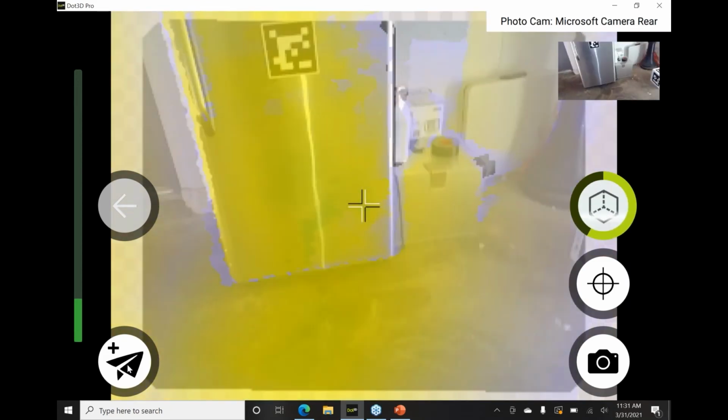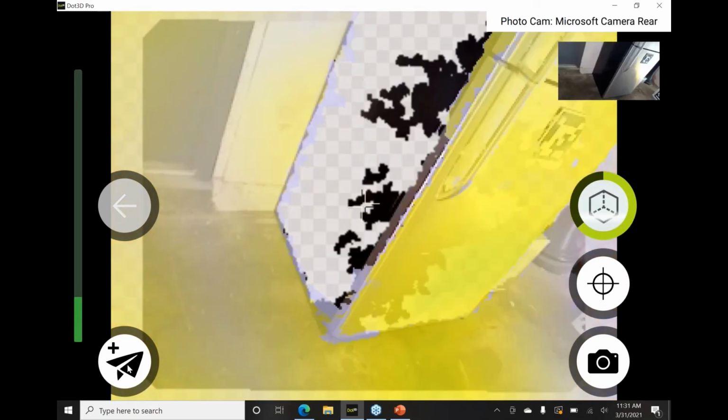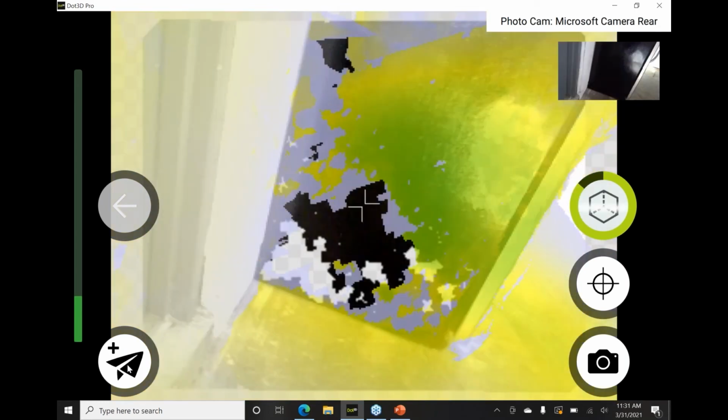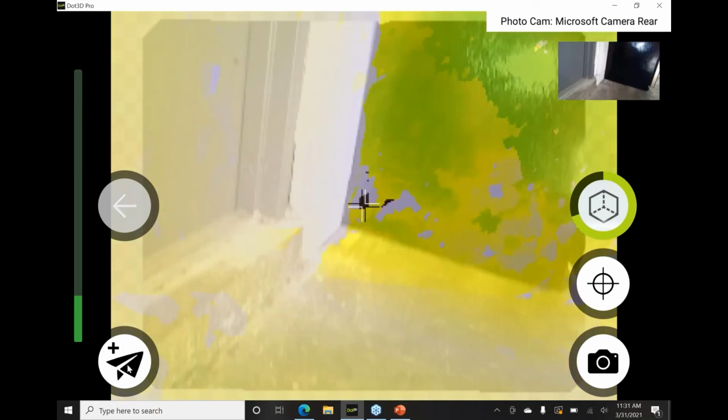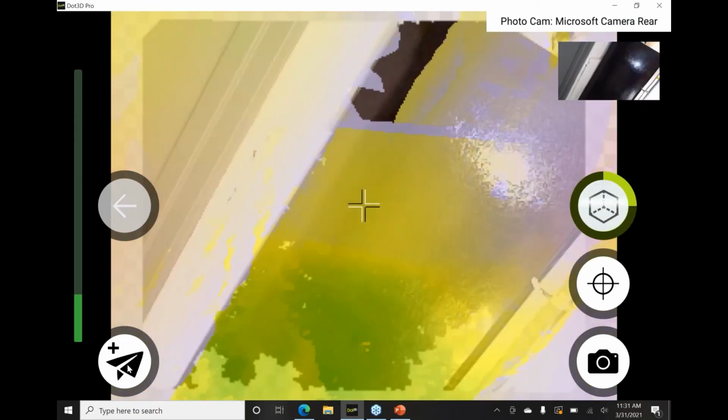Now, while shiny surfaces or dark blacks can be challenging with almost any 3D capture device, with the DPI-10 and DPI-10SR, they do a really good job at capturing them. And our software is an important part of this because you can see that it's struggling with a particular area, and you just need to get in a little closer, a little bit of a different angle or distance. And almost always, unless it's a fully polished mirror, it will fill in nicely.